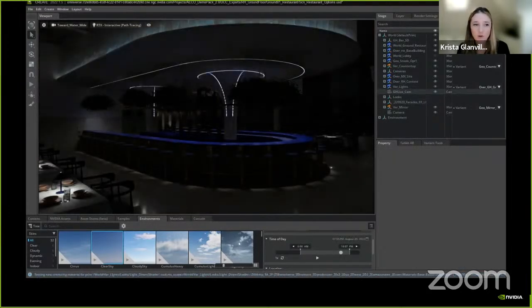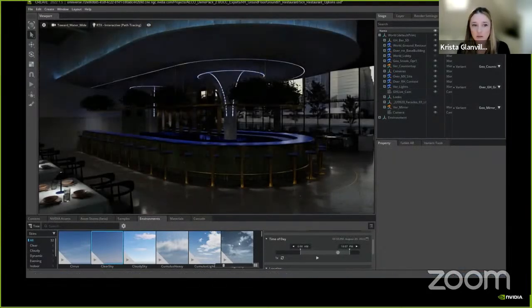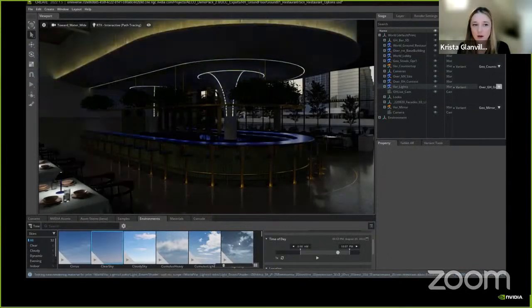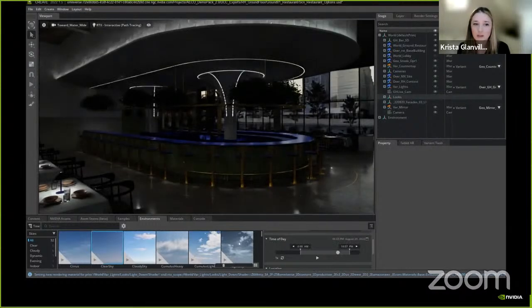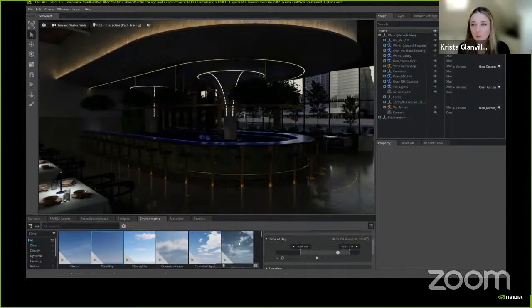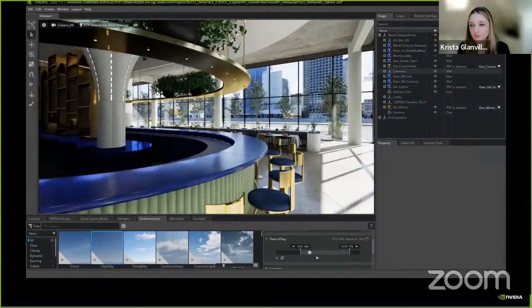And as Cobus mentioned earlier, all these options are still linked to their source files. It can all still be updated live. The lights here are actually being pulled from a Grasshopper script and tied to IES profiles. So if someone went and changed the intensity of that lighting behind the scenes, you would see that change the next time we switch over to that variant in this file.